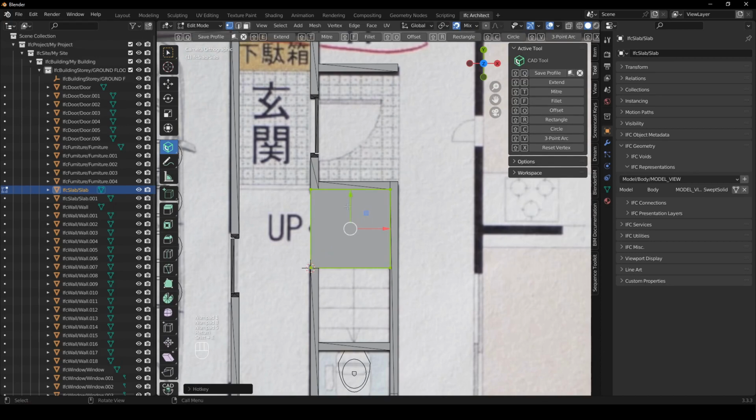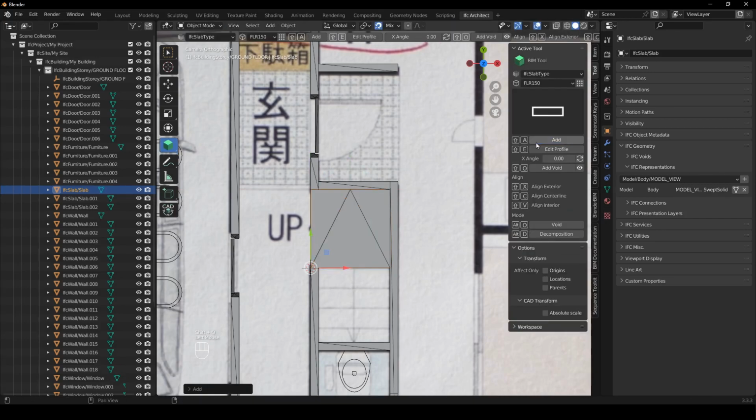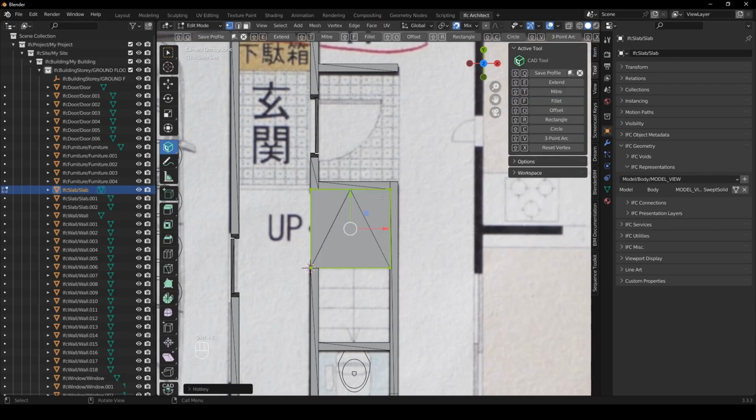I'm going to say Shift E to edit it. Press 1 so I can select vertices, and then grab that corner one and say GX so I can snap it there, and say Shift Q, and there's our first step. We can add the next one, GZ 370. Oops, not that much, which is 185 times 2.